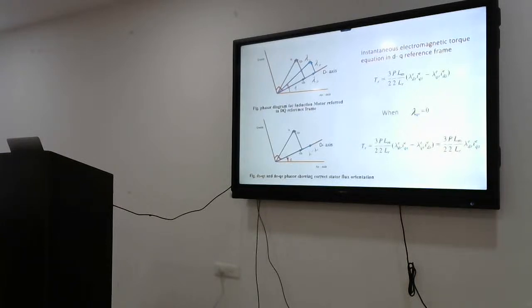Clear? Everyone understood? So by taking the transformation method, what will happen? 7th order to 4th order it will transfer. After shifting the reference point in phase with the rotor flux position, 4th order to 2nd order. After that, by using the flux control path, we can maintain the magnetizing flux as a constant. If it is a constant, then torque is directly proportional to only IQS, the Q axis component. This Q axis current we can control simply. If there is one variable, we can easily control.